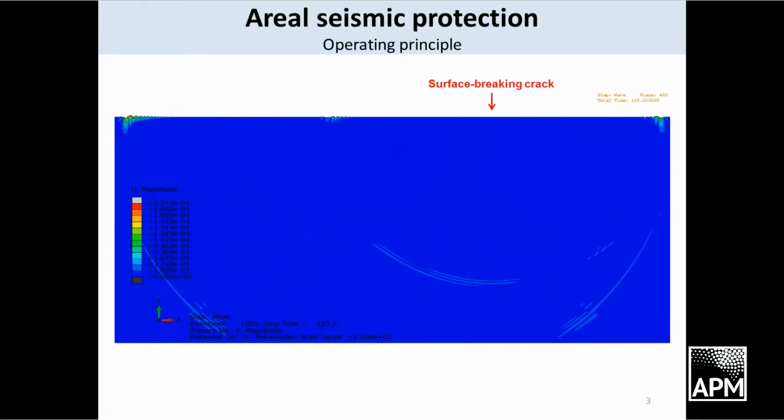It means that Rayleigh waves reflected from a barrier interfere with continuing to arrive incident waves, thus causing significantly higher seismic loads outside the barrier. It is evident that we must quantify wave reflection and transmission to determine the optimal number of cracks and their parameters.